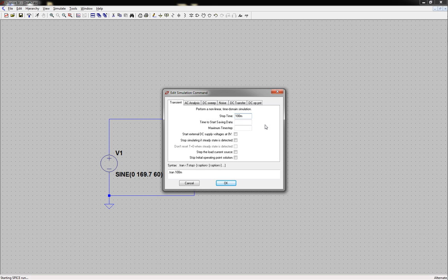You could do your 2 pi and figure out the frequency, and then remember that when you're dealing with AC waveforms, to pass from frequency to time domain or time domain to frequency domain, it's 1 over whatever you're dealing with. So if you're running at 60 hertz, which gives you 1 period, then 1 over 60 will give you the time period. So it's about 16. In fact, we could just do that real quick, just to prove it.